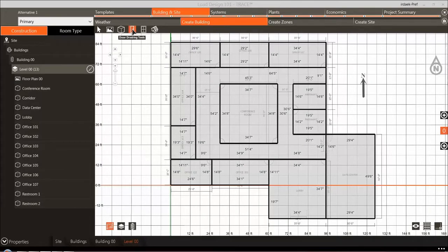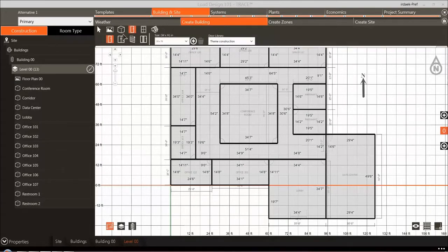Clicking the Door Tools icon will display the 4 types of doors that can be used in the building: single, double, roll-up, and sliding. You can also select the size of the door and place it on the walls according to our example drawing. To add a door, select the door type, set the desired size, and click the desired location on the wall to place it. The cursor will have a red symbol anywhere the door cannot be placed. Once you hover over a valid location for the door, then you will see the cursor return to normal.